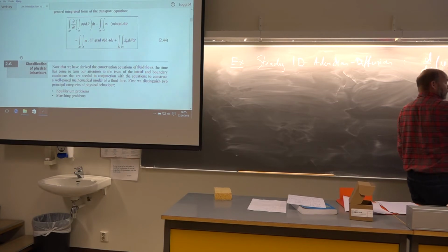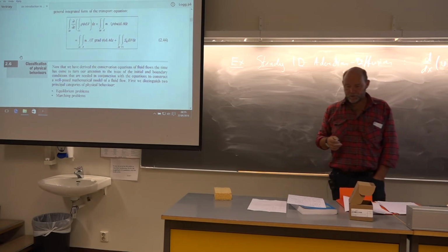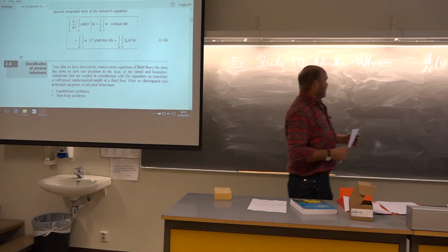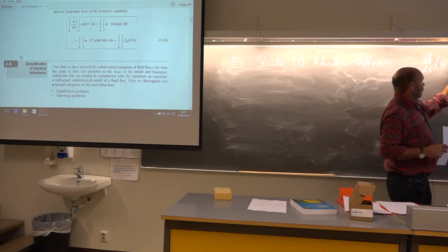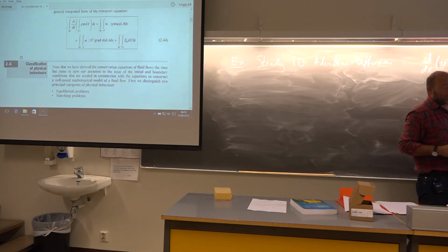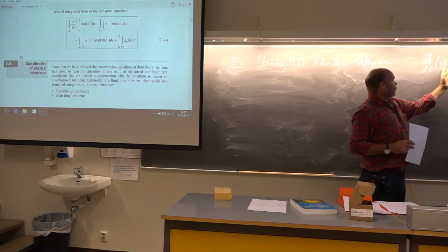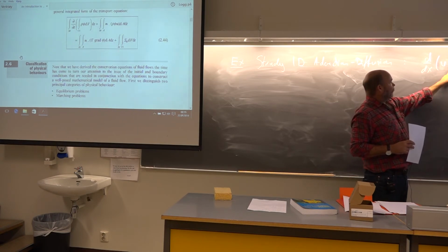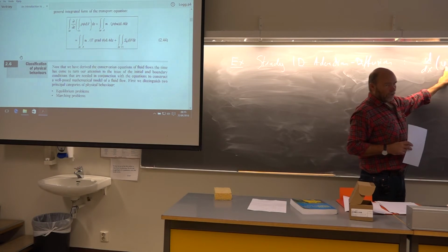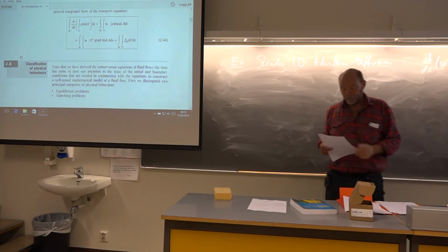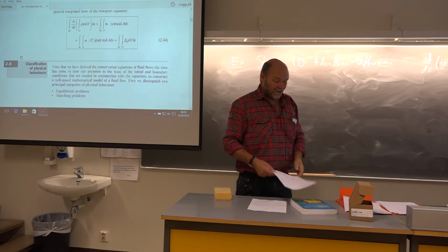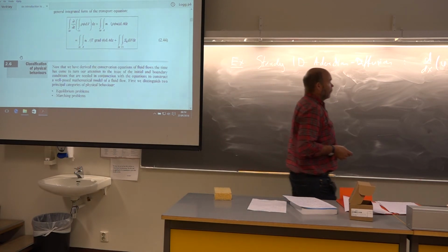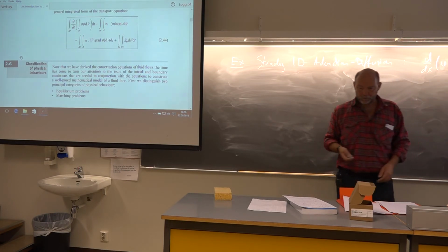Typically here they use a large gamma for the diffusion coefficient. Here I just use the viscosity directly, hence the generic unknown phi then has to be a velocity. It's a sort of trick to linearize this term. But now you see if the phi was the velocity u as an unknown, it's a non-linear equation. But we sort of say that we know the velocity u here, so it's only the unknown phi that we are focusing on.